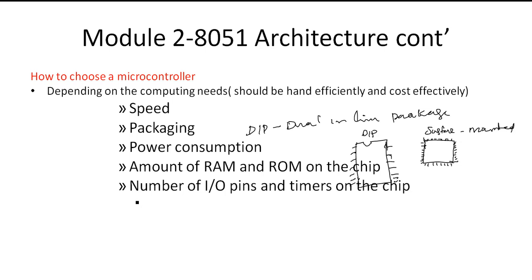They are very common. These types of microcontroller based embedded systems need a large number of IO lines. 2 or 4 or 10 will not be sufficient for such a function. So we need a microcontroller with a large number of IO lines and timers.